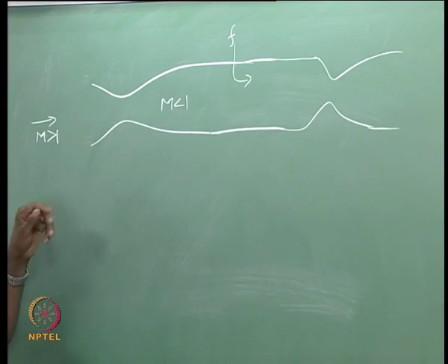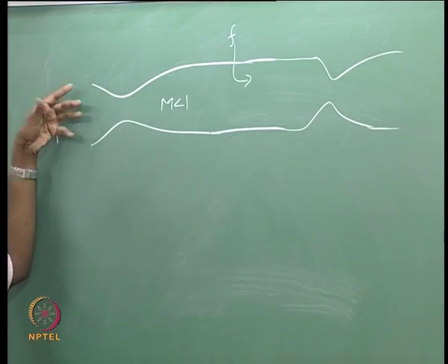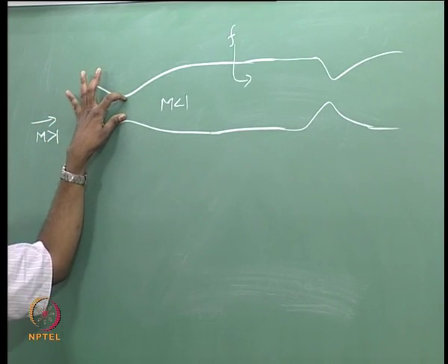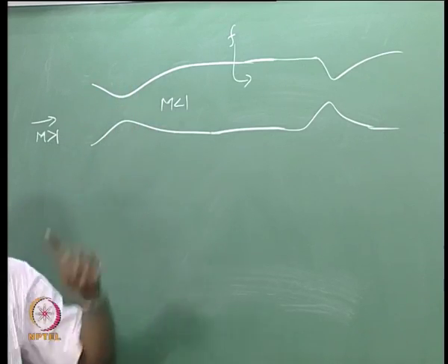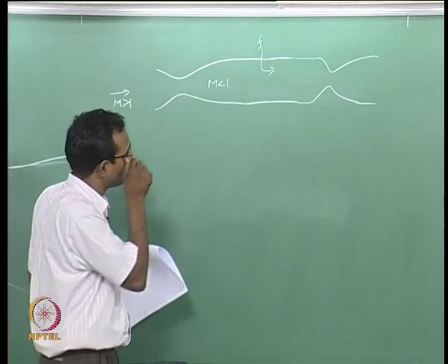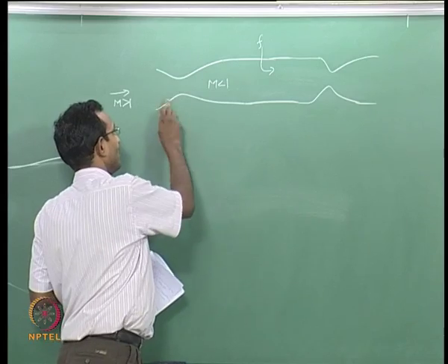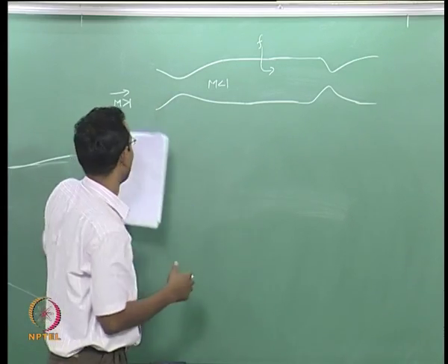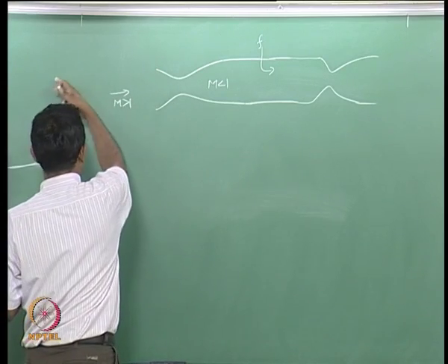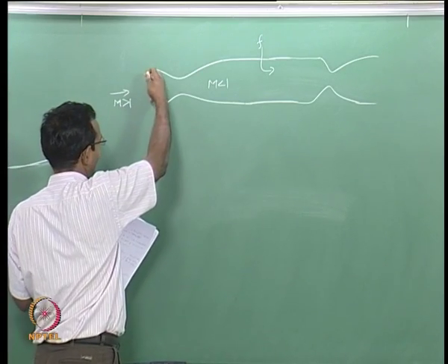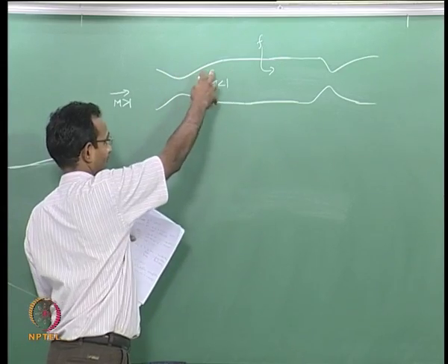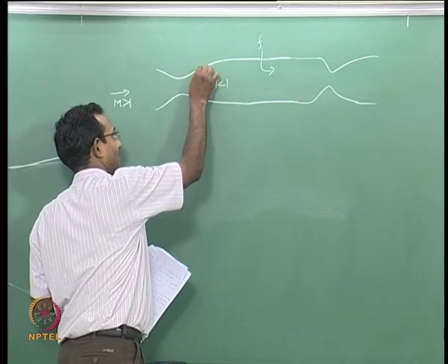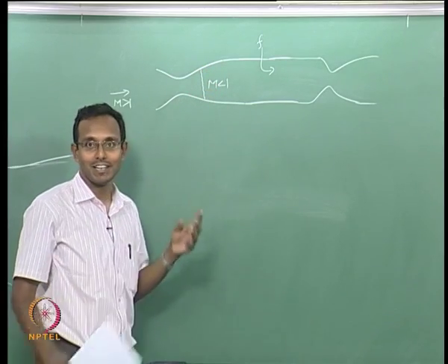I am thinking about there is incoming supersonic flow, it is going to have choking here, and it is going to go to subsonic solution. Of course, you should remember your nozzle flow conditions, this is a double throat nozzle we discussed some time back. Imagine there is one more duct here and there is a nozzle which made it supersonic flow, it goes through a second throat and it is going subsonic. If that is the case, it is as if a shock is sitting here. This is what really happens.